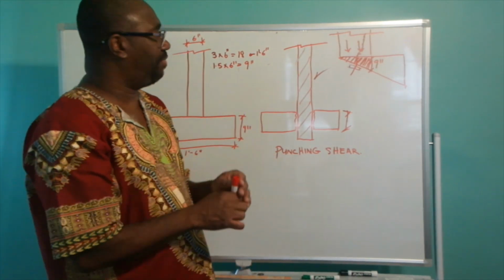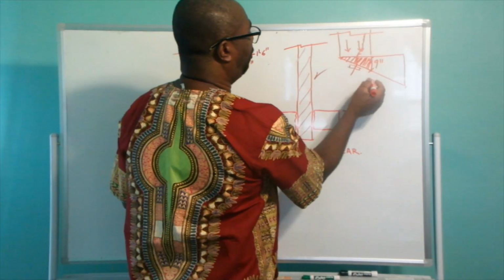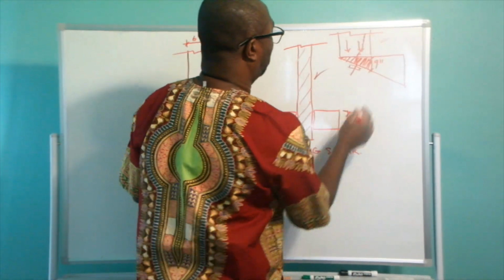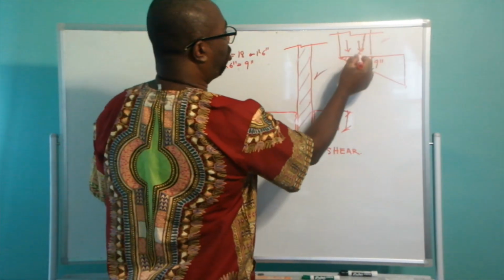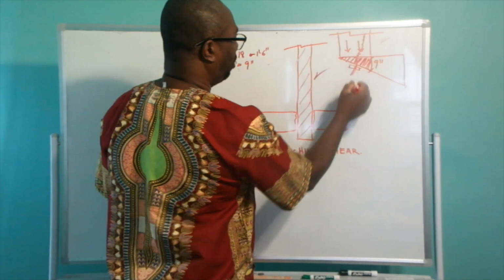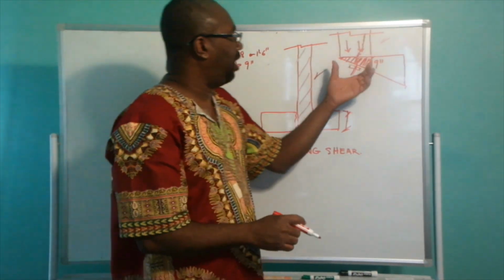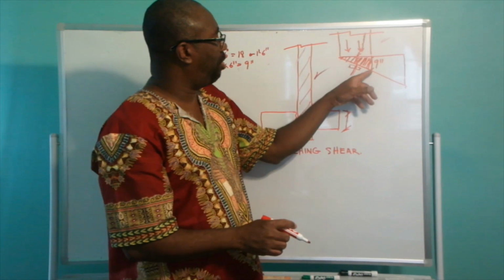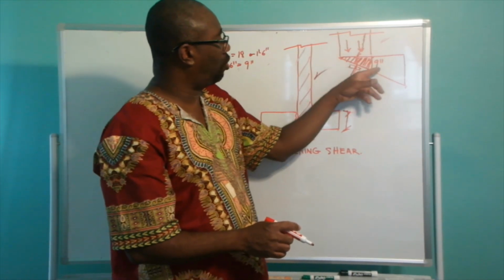And in the case of the step footing, as I've indicated before, this is the situation I'm talking about, where you're going to end up with a crack in your foundation, because the thickness from your 9 inches point here coming up the slope is going to reduce.